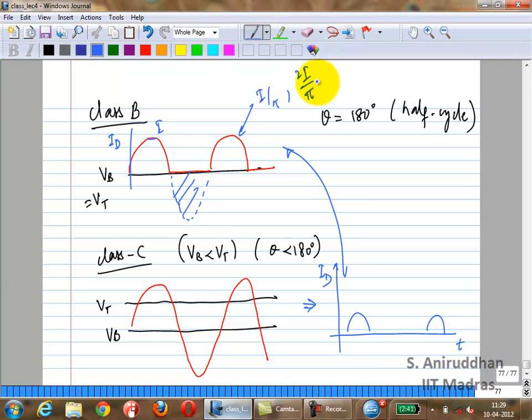Okay, but definitely the fact that it has clipped waveforms means that it is nonlinear. You are inputting just a sinusoid. You will not only get the sinusoid, you will get some harmonics of the sinusoid also, right? So that's another way to check that it's nonlinear.